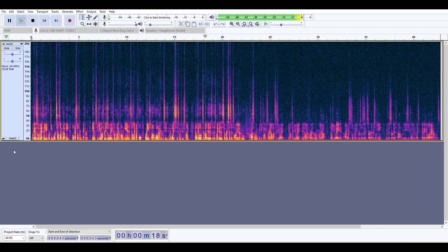Now, one thing I'm a little concerned about is that this mic is very sensitive, so I'm going to get up and move across the room and keep talking. So right now I'm about 6 feet away, and about 10 feet away, and now I'm at the far end of the room, probably about 20 feet away, and my voice is still coming through. So this is a concern, that there's so much gain with this circuit, with the AGC control even in place, that it may pick up a lot of background noise.